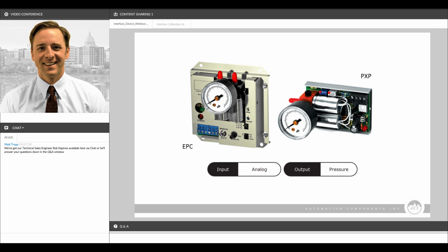We typically recommend the dual valve because you don't get the hissing sound from these devices, and it also puts less strain on your compressors because you're not constantly bleeding air.